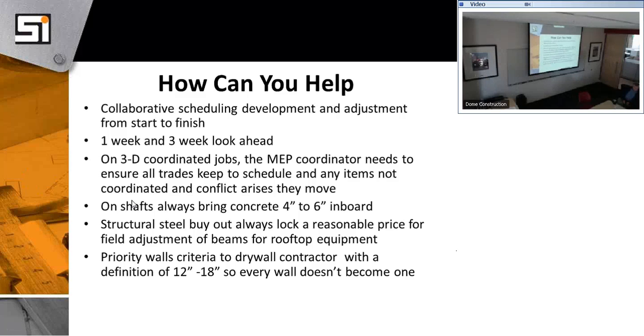Storm lines from your roof drain, graded lines from your bathroom cores, and other areas you have to be careful with, that make their way out of a main duct line or some other main utility that's coming through that's colliding with it. So focus on those kinds of things first, and usually a lot of your headaches go away when you take care of the graded line.